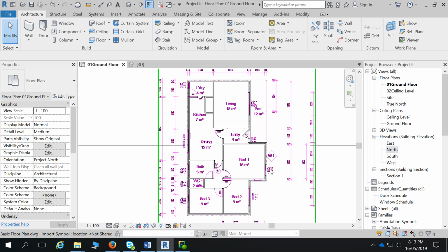So the thing when you put the windows in Revit, they would go at random, because these were all really low. Is that the consistent one? Like, if the window's 600 high, you still want it at 2100. Yeah. But I'm going to show you the easy way. I'm going to put another level in, and then align everything along it so it's going up and down for you.